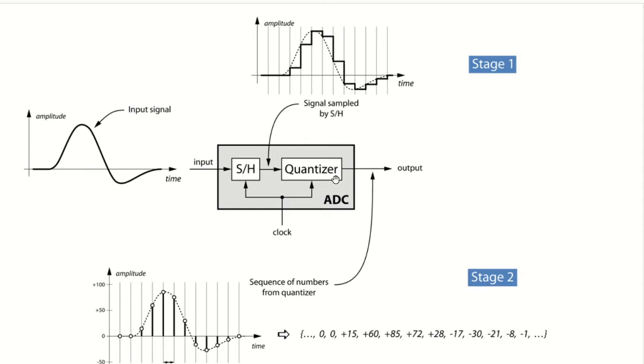So the process of the analog to digital converter starts from this, for example, analog signal, which is amplitude versus time. And then you sample. What is sampling? It is using a sampling period, and at each period we measure the voltage. So we take this point, and I say that my signal will not change over one sampling period. And then at the next sampling period, I take a flash, or an image, of the signal.